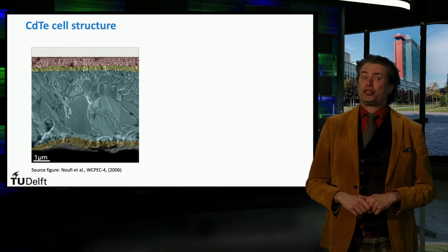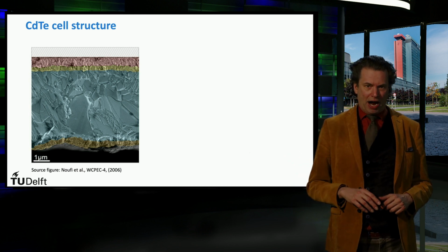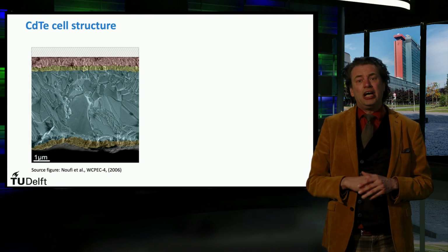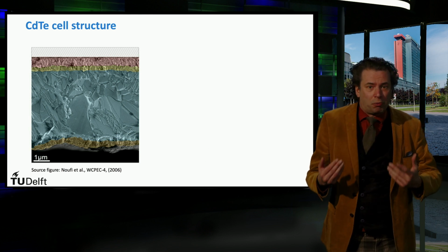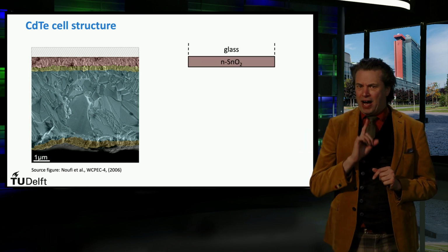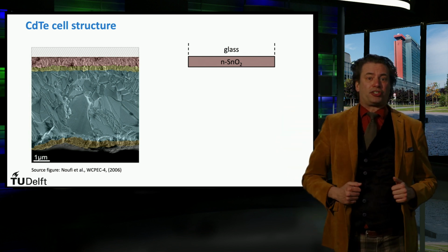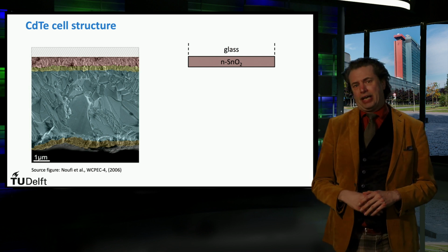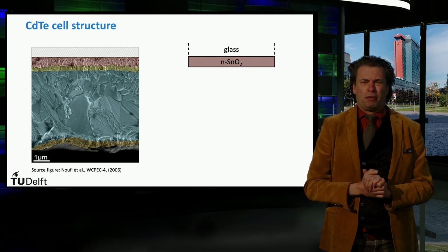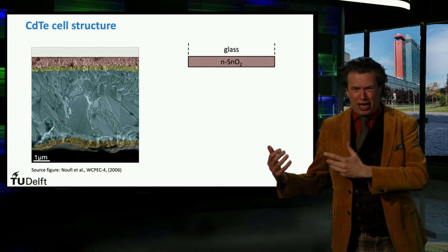This illustration shows the cross-section of a standard cadmium telluride based solar cell with an absorber layer of about 4 micrometers. In contrast with the previously demonstrated CIGS technology, a cadmium telluride solar cell is most commonly deposited in a superstrate configuration. This implies that the contact layer at the top of the structure, where the light will enter the solar cell, is deposited first. And this layer is therefore required to be transparent. Most commonly, forms of n-type doped tin oxide or glass are used.